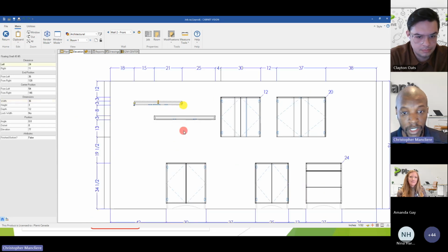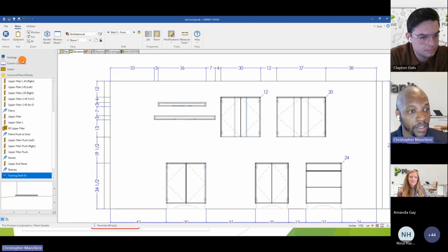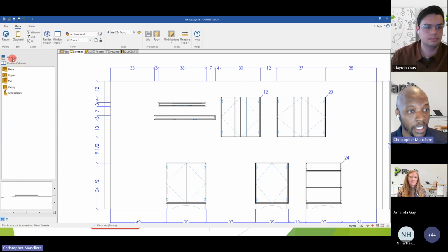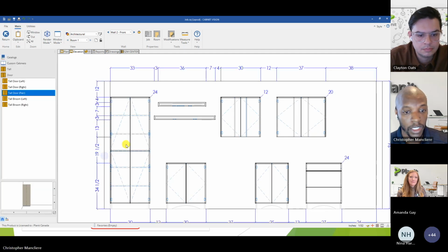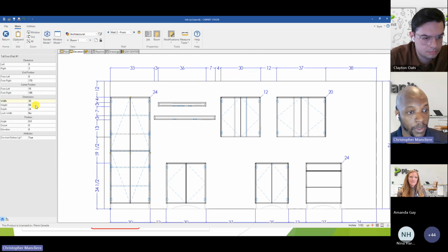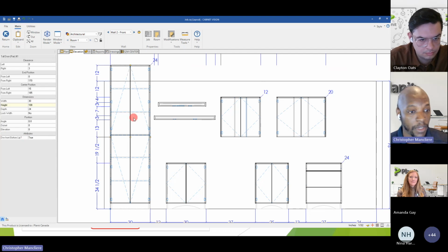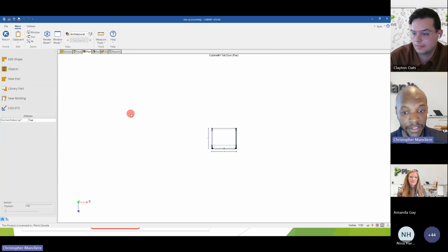and I'll just move this on the side, is if you have a part that you want to split, you can do it in one click with shaping. So let's say I put a tall assembly with a pair door, and let's say this is, for example, 108. And let's say my cabinet is 108, but I only have 96-inch material. So maybe I know that my back will not fit on my CNC machine. So what you can do is if you edit this assembly,